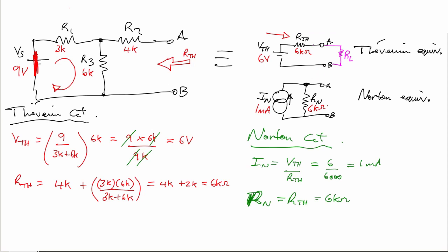What's the best value of load resistor that goes there so that I can achieve maximum power transfer from the battery? We'll be able to plot various values of load resistor in the Micro-Cap simulator. So that's what we're going to do next: have a look in the Micro-Cap simulator and produce all of these analyses there.